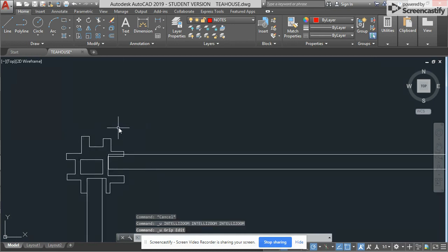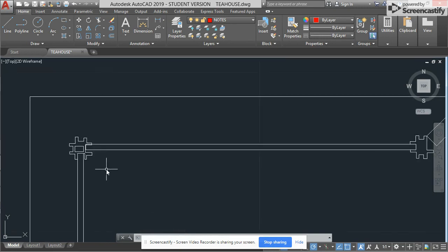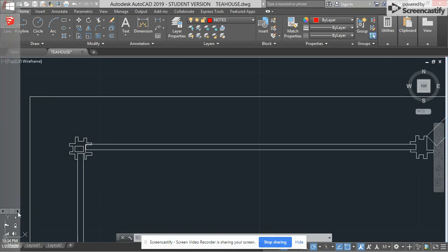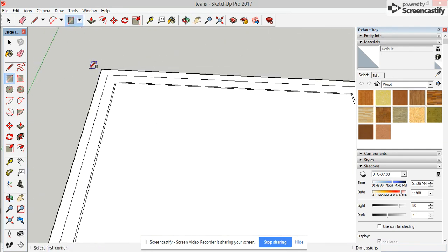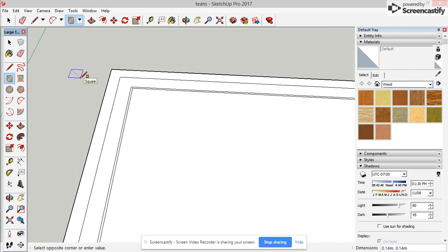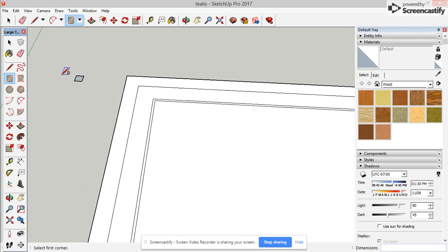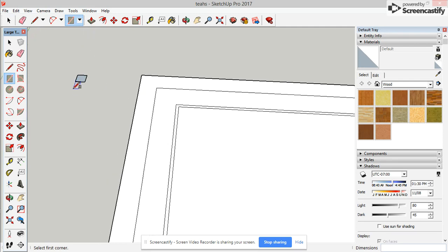These plus signs, the box size of it is 0.07 by 0.07. So we're not going to go to the trouble of locating exactly where this corner starts. We're going to place it on this corner of the glass. So I know it's 0.07 by 0.07. So I'm going to go back here. I'm going to make a fake one right over here off by itself. 0.07, comma, 0.07. The dimensions themselves aren't rounded, but it shows rounded. So there we go. There's our base.